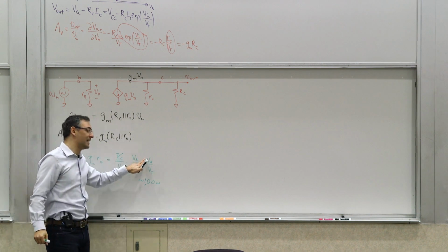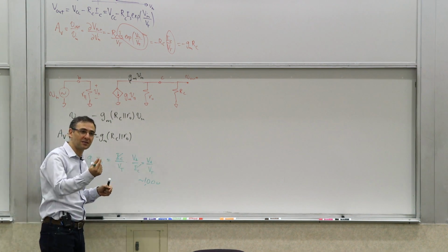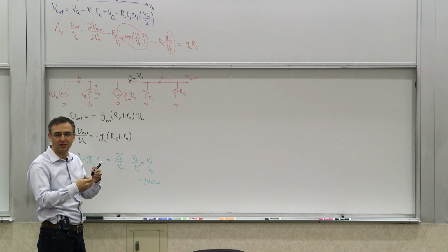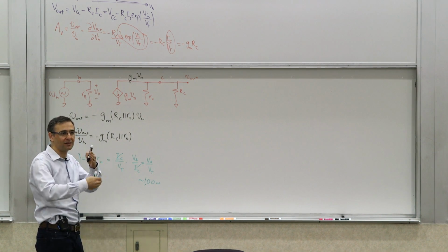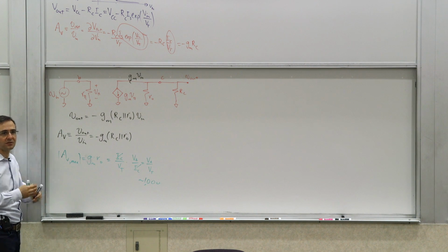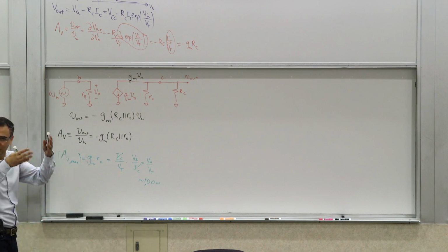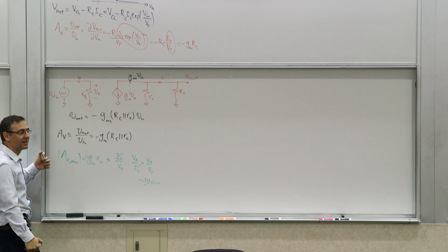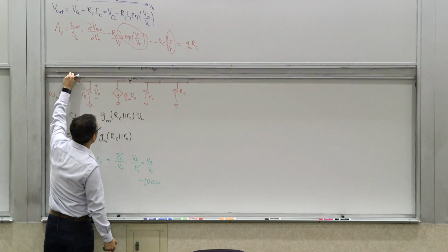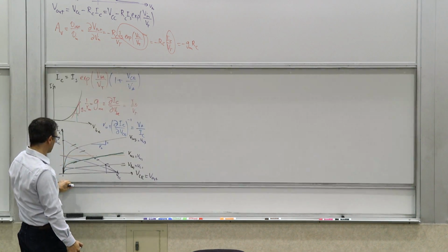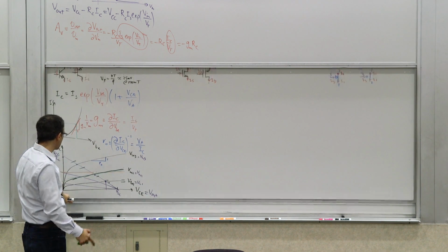And we know VA depends, for example, on the thickness of the base and the doping concentration. We adjusted the doping concentration of the base and collector relatively to make sure that most of the depletion region falls in the collector side. So all of that good stuff that we talked about plays a role in this. Okay, so that's for that. There was one more thing I want to talk about.